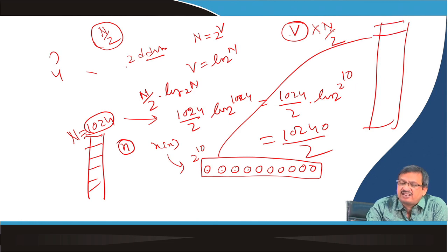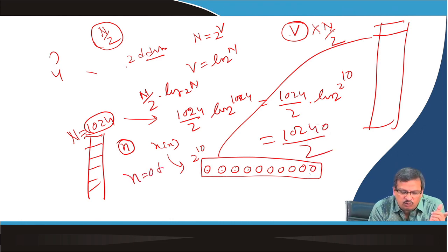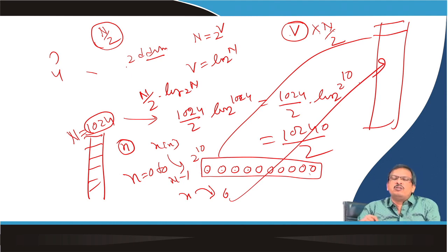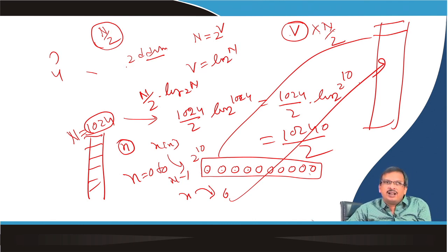When I access the signal for doing FFT, I will access it in bit reverse mode. Whatever the index n, it varies from 0 to N minus 1. I get the n, take the bit reverse, then access the corresponding signal. When I access the 0th signal, it is accessed; when n equals 1, I do the bit reverse. Whatever index comes, I access that signal and compute the FFT algorithm.